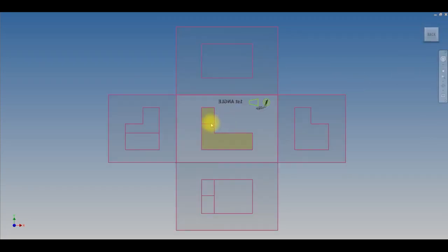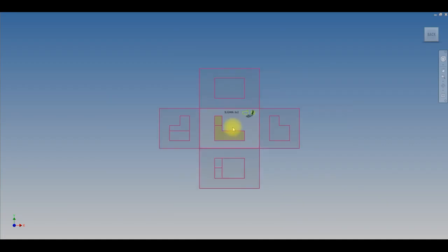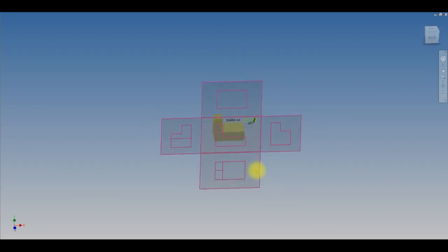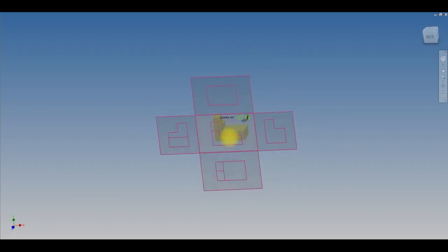So the way that you look at your drawings, that's why I said that if somebody working in first angle projection gives a drawing to somebody that works in third angle projection, they would see this back to front. Normally a good tradesman will pick that up and say, hey, this just doesn't look right, because they'll see this shape and it will be different.